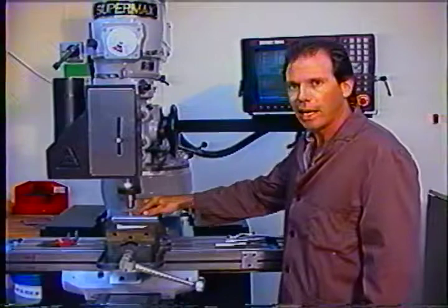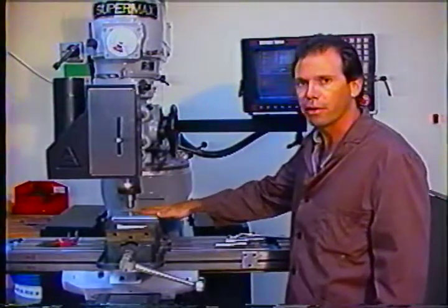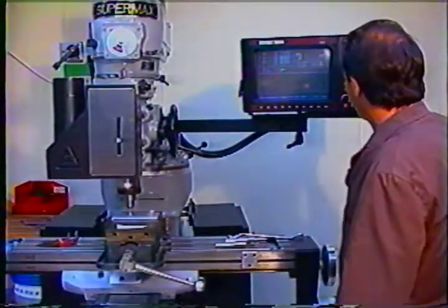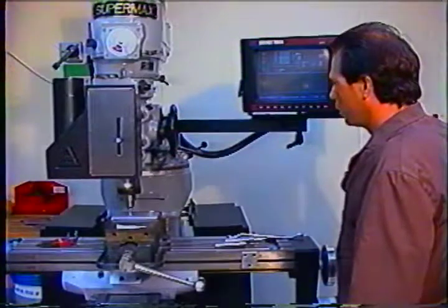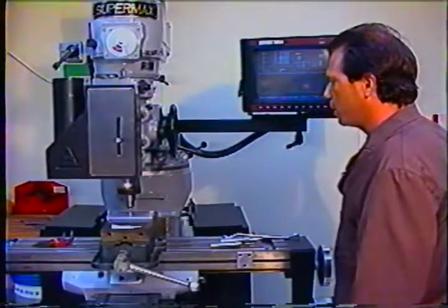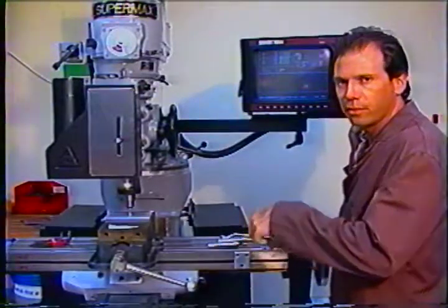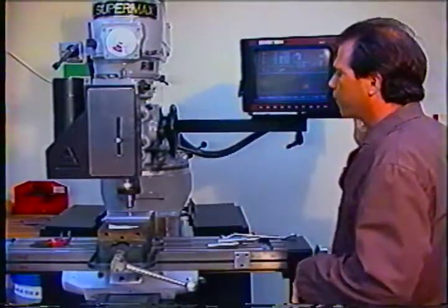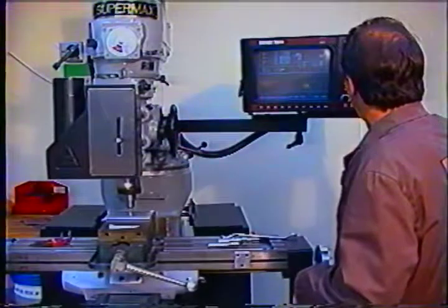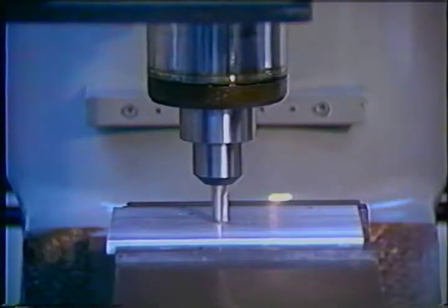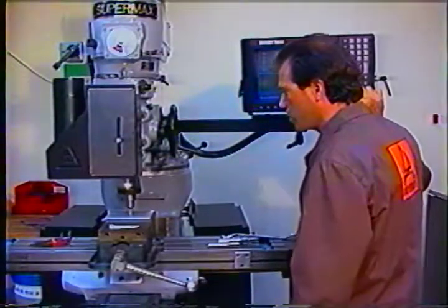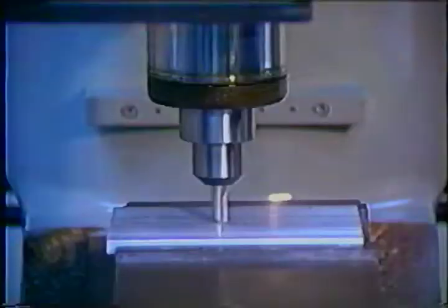You can take some blue dye, fan it out on the part here and let it dry, and move your tool over the blue dye and turn the spindle on, and then jog down 1,000th or 1/10th at a time until you see the blue dye disappear. So I'll turn my spindle on forward. I'll go into jog 10, which is 1,000th at a time, and I'll move it down till I see the aluminum be touched by the end mill.